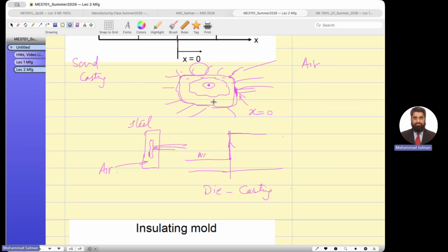If you have molten metal, let me ask you, if this solidifies faster, or if this solidifies faster, does it matter? If the riser solidifies faster than the casting, you will not be able to remove the shrinkage loss. You have to reduce the time of solidification in the riser. Otherwise, it will not compensate the shrinkage losses. If it is already solid, faster than the casting itself, then it will not be able to push the metal through the riser to cover the shrinkage. So therefore, the spherical shapes or maybe different shapes, have different time constants. You see my point? Time constant.